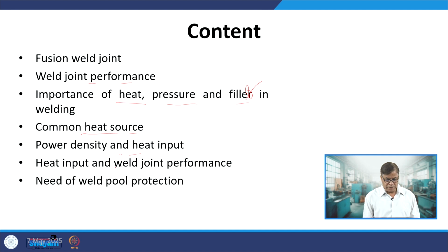So how the heat input affects the weld joint performance, and additionally, when fusion welding is carried out, the heat generated during the welding is high, and the significant increase in temperature of the parent metal leads to the interaction of the metal with the atmospheric gases. So that contaminates the weld joints and degrades the quality of the weld joints. Therefore it is important to protect the weld pool.